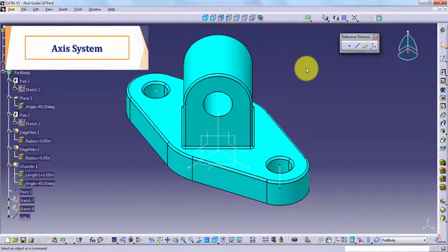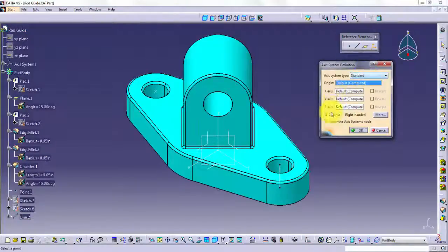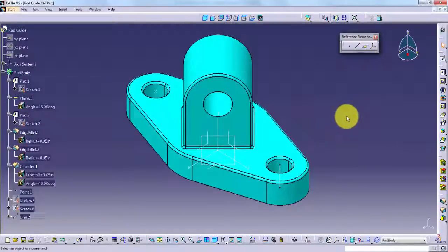An axis system is comprised of a coordinate system, a reference point, 3 reference planes, and 3 reference lines. These combine to form one axis system but behave as individual items depending on the application. You can select each of the components as reference geometry for most operations. This is an advantage over reference planes and lines, since it is a single feature rather than 7.